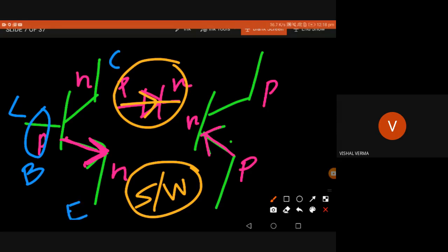This doesn't matter here, because for the transistor switch we assume the transistor is symmetric. So don't need to worry about base, collector and so on. If the base of NPN is given a low signal or low current, it is just an open circuit. There is no connection between collector and emitter, and the switch is off. And if it is a high signal, high current, it is on. Collector and emitter are shorted.